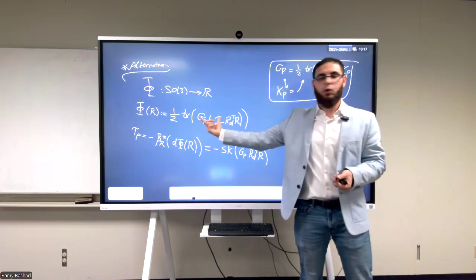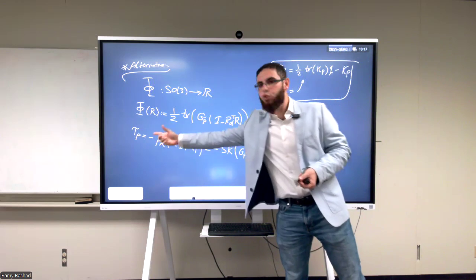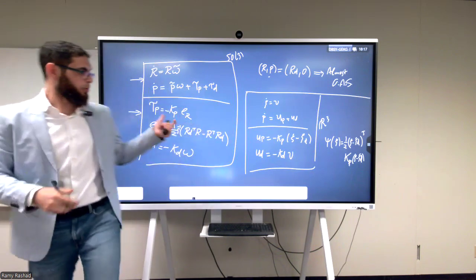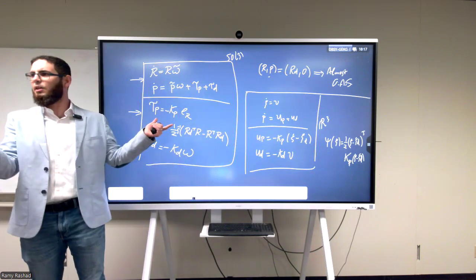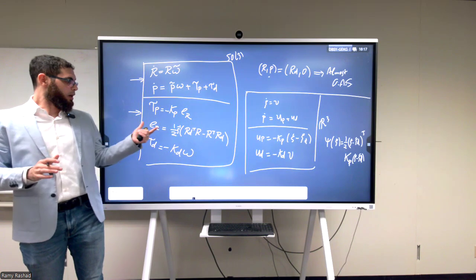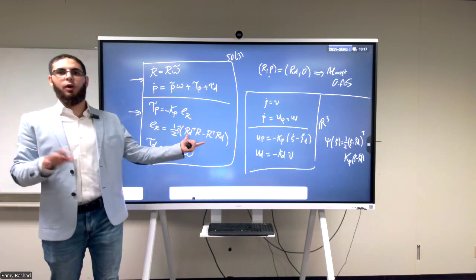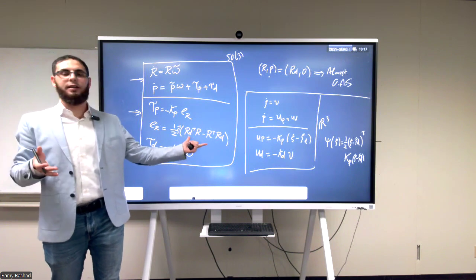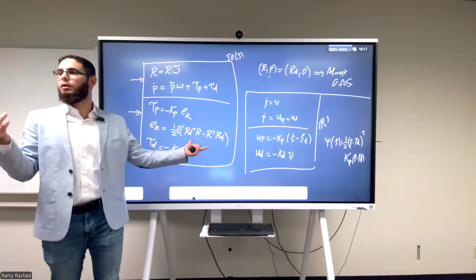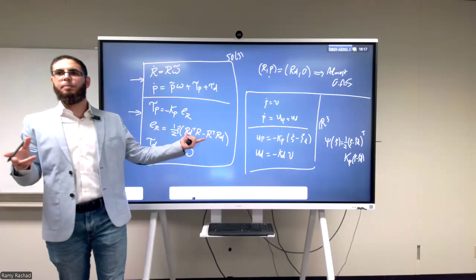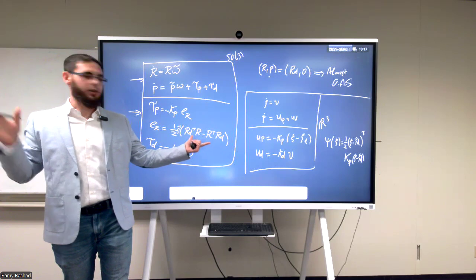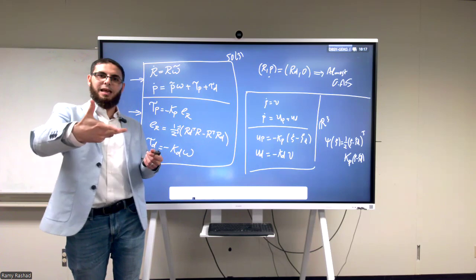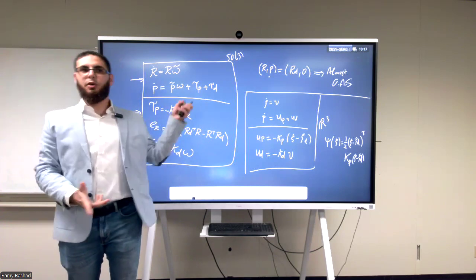And then with this Lyapunov function, when you take the gradient of it, you truly get a torque. This one that you find. I started with this one because it's simpler. We didn't start with the difference between KP and GP and all of that. Also, this one is in a very popular paper. Anyone who has seen any paper on geometric control on quadrotors will find a very famous paper by Taeyoung Lee, a 2010 paper with 1,300 citations. It's really one of the things that, if you see any quadrotor able to recover from a flip, it's because of this controller.